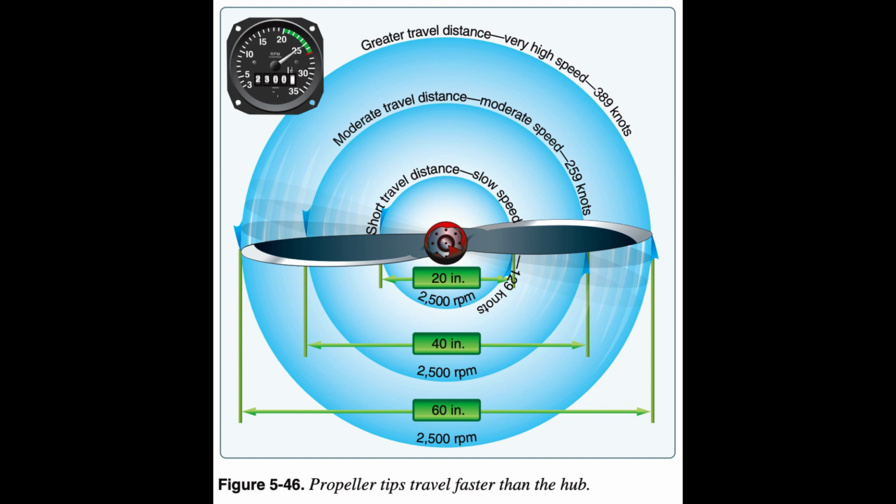After the takeoff climb is established in an aircraft having a controllable pitch propeller, the pilot reduces the power output of the engine to climb power by first decreasing the manifold pressure and then increasing the blade angle to lower the RPM. At cruising altitude, when the aircraft is in level flight and less power is required than is used in takeoff or climb, the pilot again reduces engine power by reducing the manifold pressure and then increasing the blade angle to decrease the RPM. Again, this provides a torque requirement to match the reduced engine power.